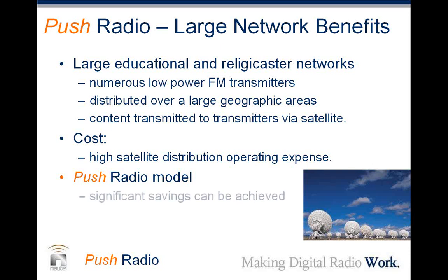In the push radio model, you could potentially get rid of that satellite distribution expense completely, and save a tremendous amount of money. And meanwhile, since the satellite, which suffers from sun fade, is gone, the reliability potentially could be improved. And while you could say, okay, well, what about the reliability of the IP network? Remember that with push radio, with storage locally in the transmitter and local execution of a playlist, if the internet goes down, all you've lost is the ability to update the playlist. The radio station is still continuing on the air.